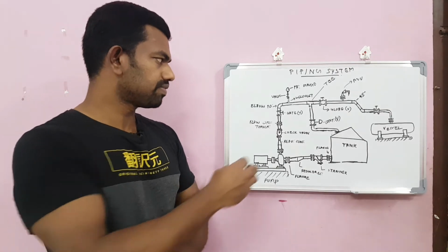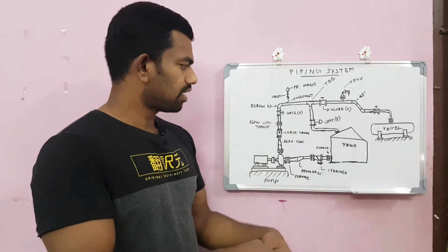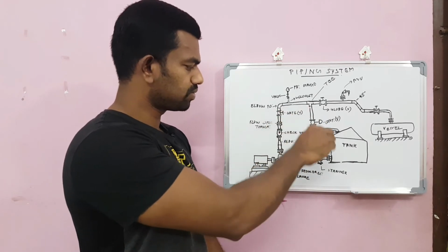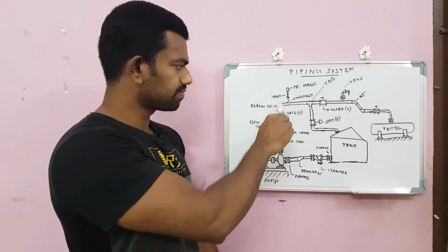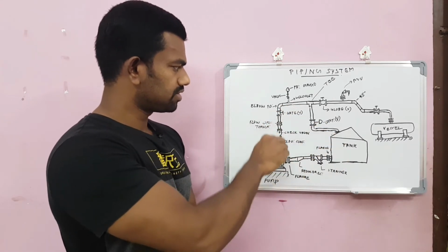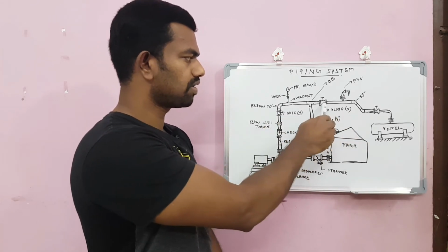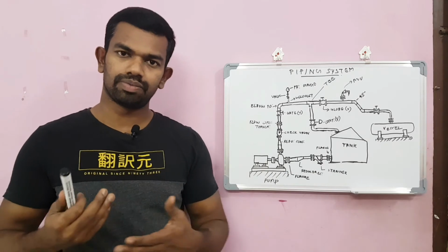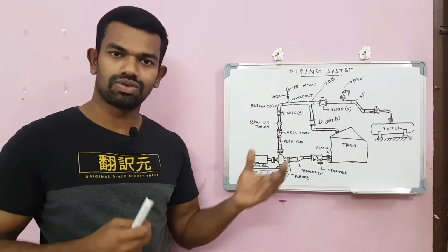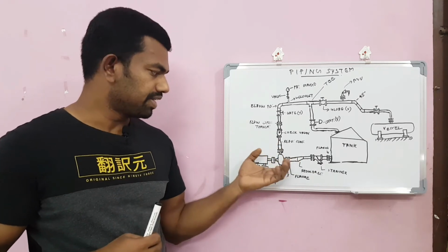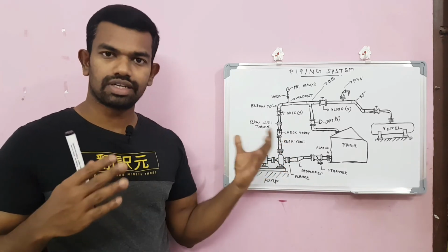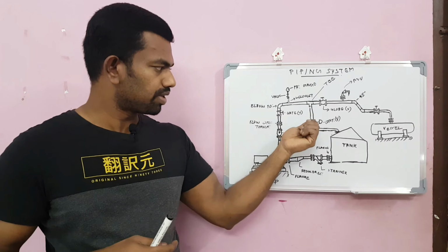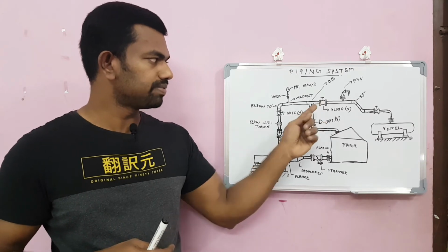For this purpose we close this valve and open this valve, and the flow will circulate in this direction. It will not go here because this valve is closed and this one is open, and we can verify the pressure, temperature, whatever parameters or troubleshooting, and finish. Once everything is ready and normal, we can put it in operation position, closing one valve and opening the other.